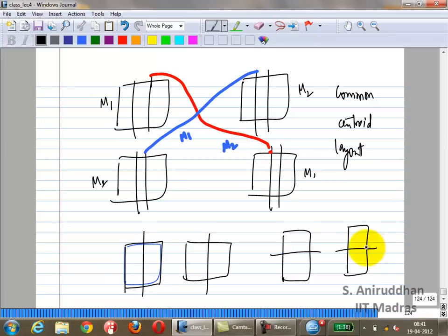No. These are two independent transistors, but you want them to be matched. Okay. Well, let's say they don't share a common source, but you still want them to be matched. Let us say it's a replica. Remember that op amp we had, this replica in the common mode feedback loop. Let us say these are two replicas, because one is a replica of the other. Quite often you would prefer to do the second case.